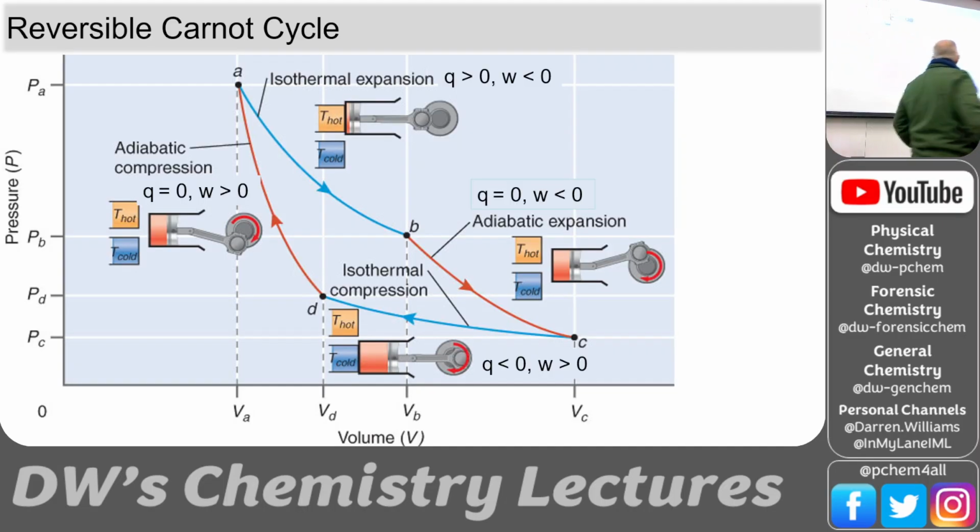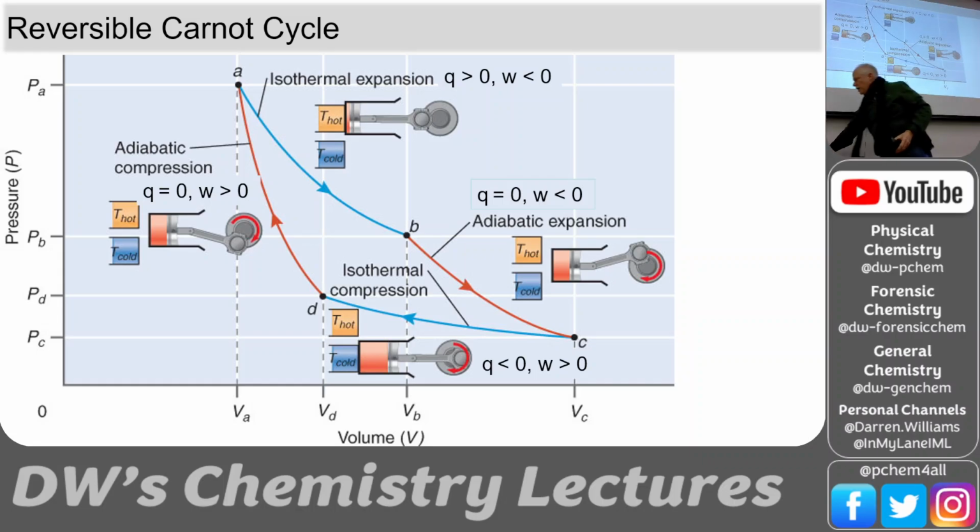So here's the Carnot cycle with pistons put on it. At the hot isotherm, that's when we're pushing that gas. The gas is pushing the piston down. Adiabat, we kind of lose the ability to put heat into it because it's happening so fast. We've got some momentum to the engine, and it finishes out that stroke. So this is the full stroke. Volume B is the minimum volume. Volume C is the maximum volume.